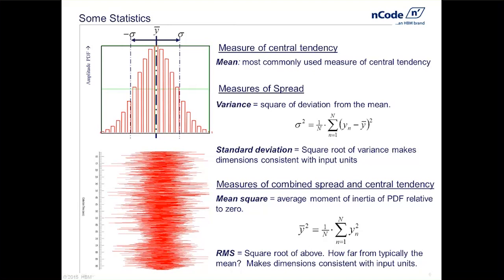All right, guys, so getting back to the last item on the slide would be RMS. Yet one more way to describe some statistics about our measured data. And that would be describing how far we are from the mean, or what is the area or the energy within our signal. So these are all some statistical things that we might be looking at, but yet still doesn't really describe the frequency content of our vibration.